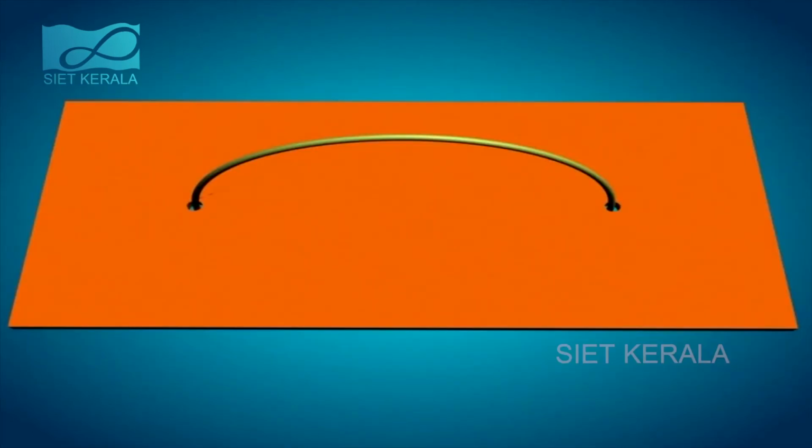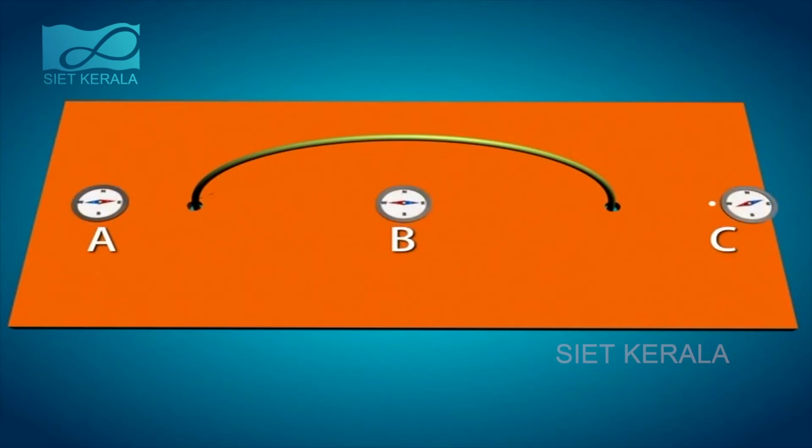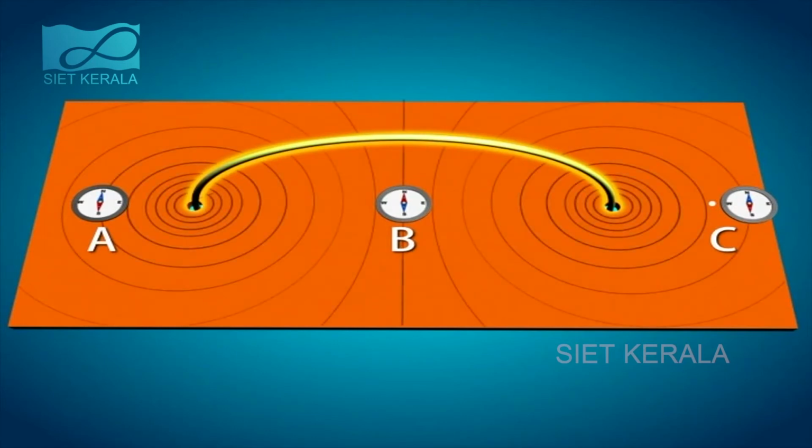At the center of the circular wire, the curvature disappears and the flux line appears as a straight line. The conclusion here is that a circular coil of wire behaves like a magnet with a north pole on one side and a south pole on the other side. We can see what happens if the number of turns of the coil is increased. More iron filings are thickly arranged around the wire. That is, the flux density is increased when the number of turns of the coil is increased.